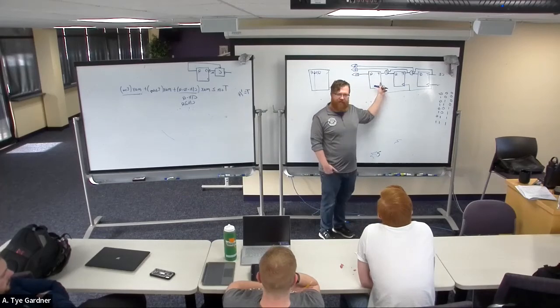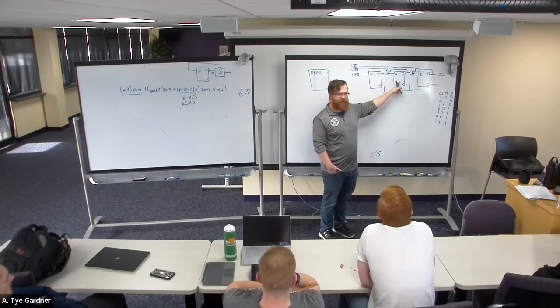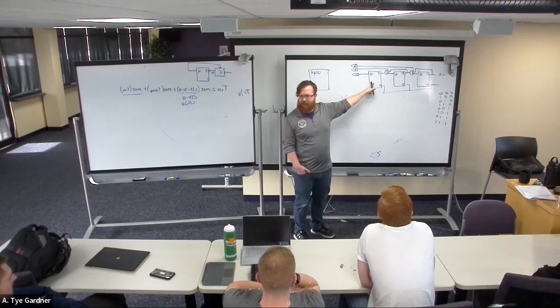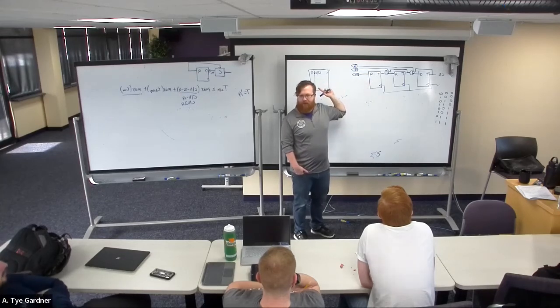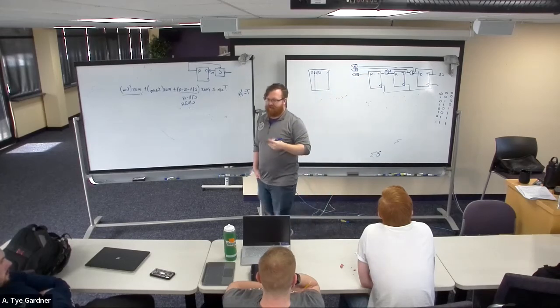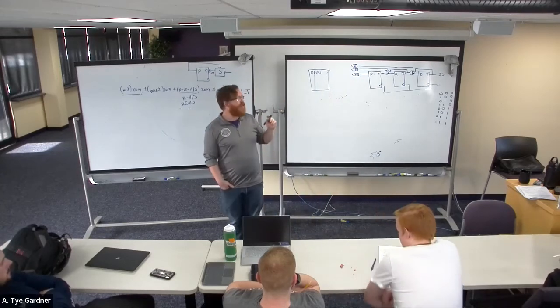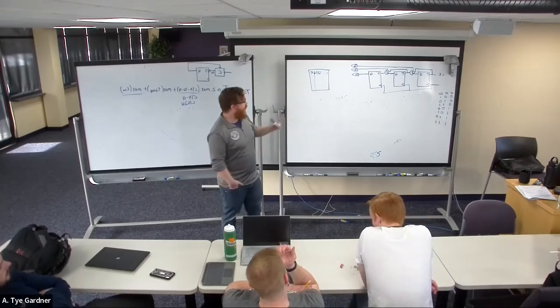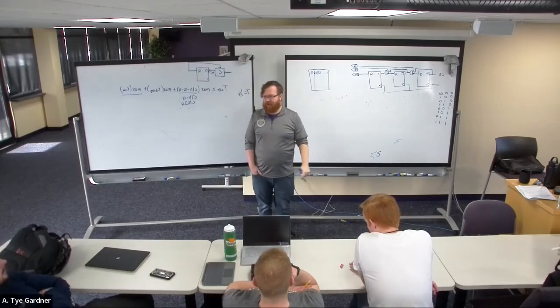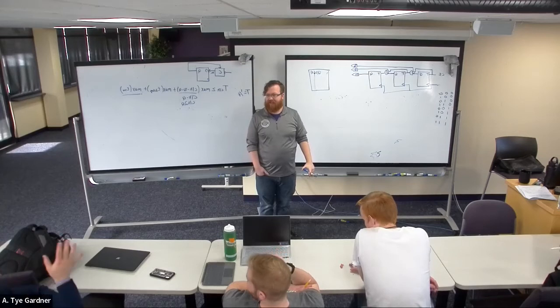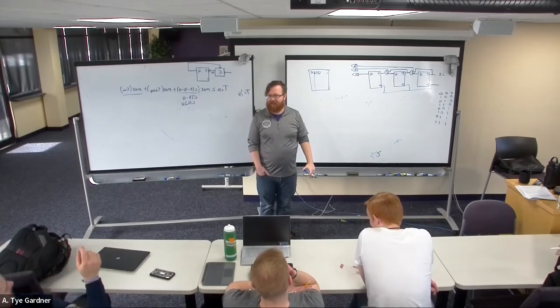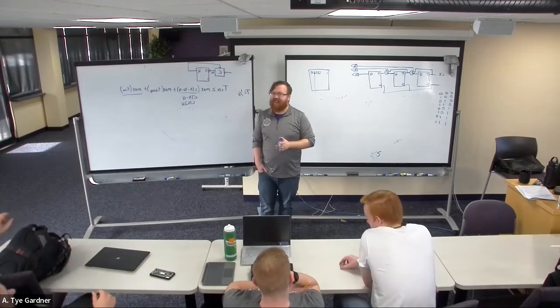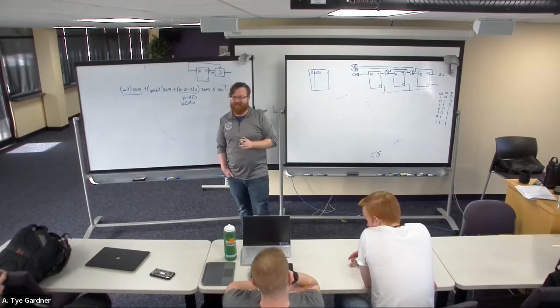But this one's not changing that fast, is it? Because this one turns on and off at the rate of, well, half, right? So that's now 50 megahertz. This is now 25 megahertz. And I do this 8 or 12 more times, and now I'm starting to get into reasonable clock speeds. So this is also what we would call a clock divider. It slows the clock down for us. We can use the output of one of these as a slow clock. So you could take that and just make a bunch and ignore your other outputs like Q0, Q1, however many, and just use your last one as a nice slow clock that we could see as a counter.